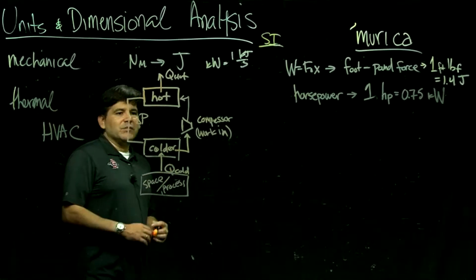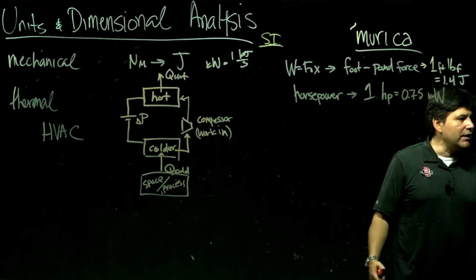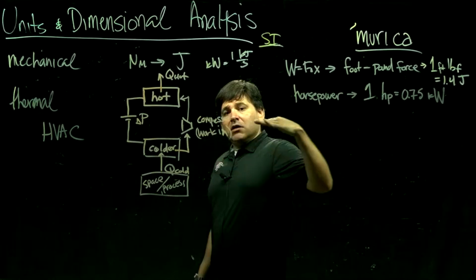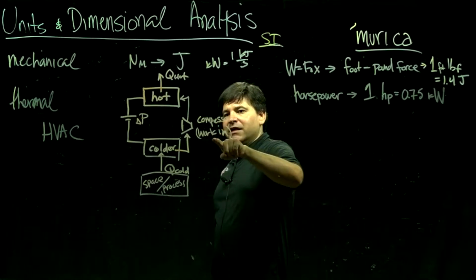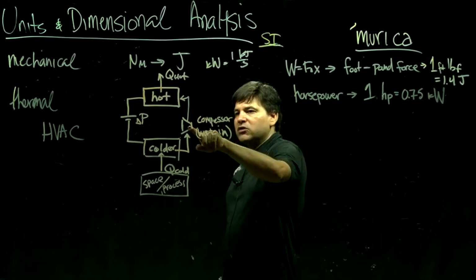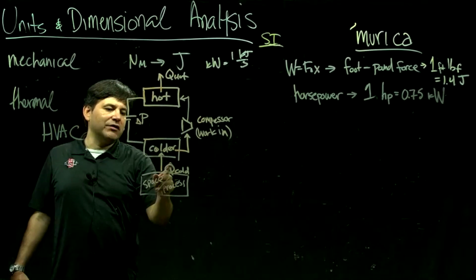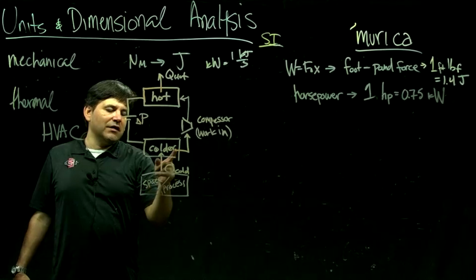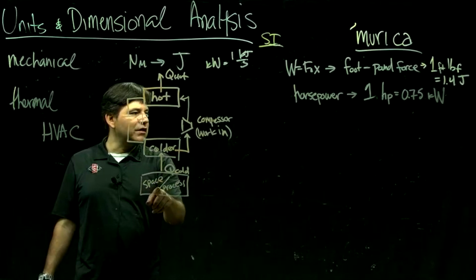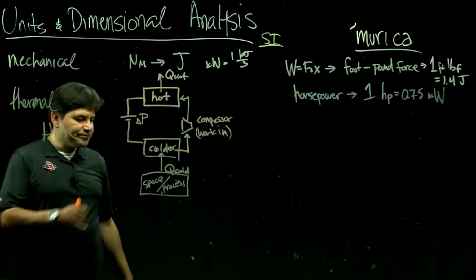So we have some energies here. As we know, to get a refrigerator working, to get our air conditioner working, most of the time we plug it into some electricity. So there's mechanical work of electricity coming in to power the compressor motor, but there's also heat transfer at high temperatures out, and heat transfer at low temperatures into the refrigeration system, out of some space, my seltzer, the room, or some industrial process of keeping things cool.